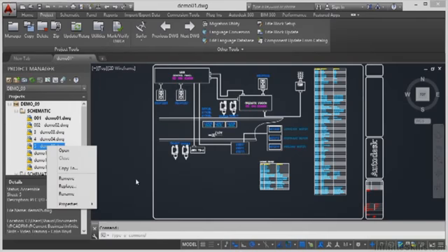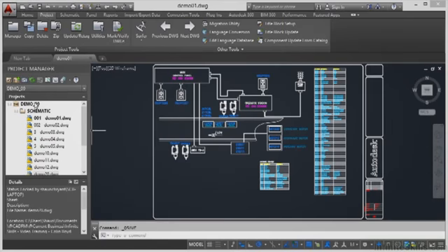So let's have a look now at descriptions on drawings in your AutoCAD Electrical project. I've got Demo 09 open still as the project, and at the moment I've got drawing 001 Demo 01.dwg open. What I'm going to do is do a quick save on that, and you'll see there, if I go here, it says file name Demo 20. I just need to refresh the list. If I refresh that now and then double click here, you can see drawing 01 actually does have a description in the details pane there, flow and interconnection diagram.